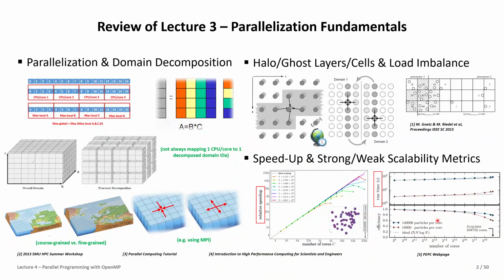And again, we see quite a difference here. We changed the particles per core. We didn't change them here. They remain the same, right? In strong scaling plots. In weak scaling plots, we give the cores more work. In terms of getting more cores, the simulation gets bigger because we keep the particles per core constant. And with this, we are filling huge machines. You see here 460,000 cores, even on an older HPC system, but it doesn't matter.